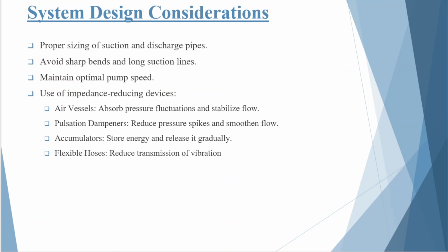Finally, when acceleration head cannot be reduced sufficiently through piping design alone, engineers install special hydraulic devices such as air vessels and pulsation dampeners. These devices significantly improve the hydraulic performance of reciprocating pump systems.